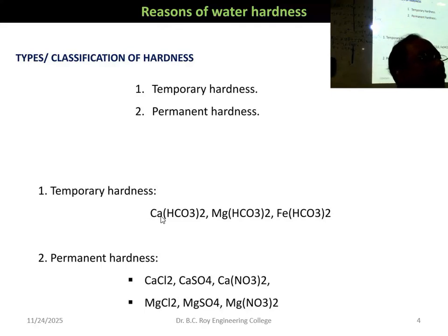Lime is used for several purposes. Number one, maintaining pH. Number two, removal of hardness. If there is a temporary hardness, it can be removed. Just take slaked lime water. Lime water. Don't give huge amount of lime, but you have to use lime water. Otherwise, the well will be filled up by lime. So you have to add that water, not the insoluble portion. Only the soluble portion you have to add.